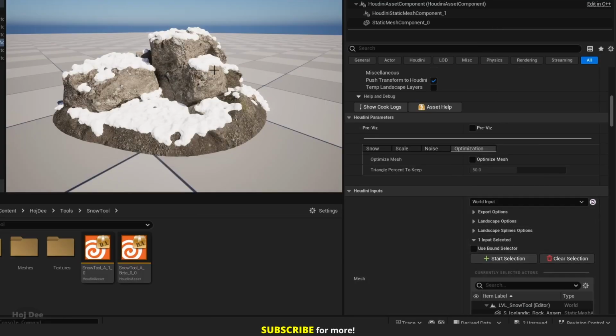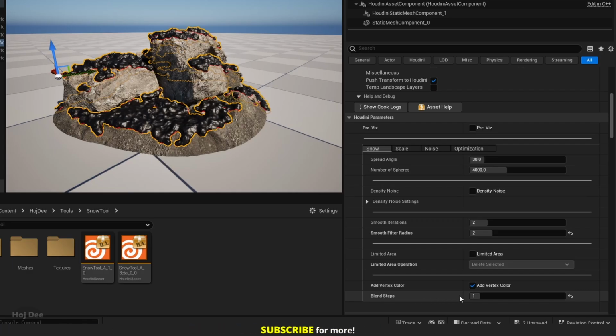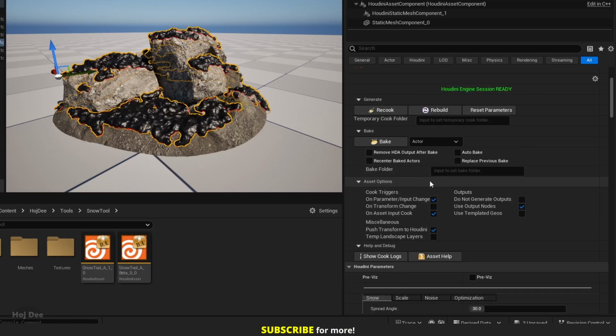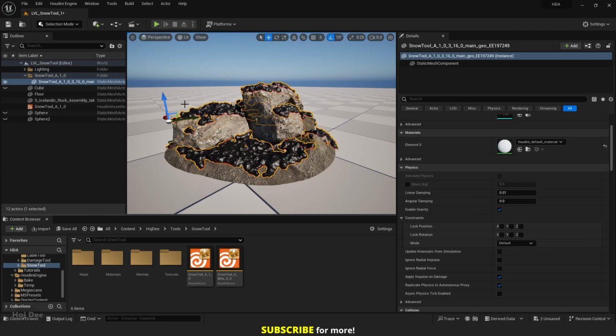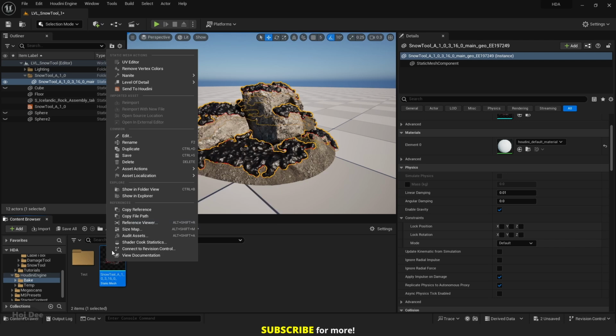After we're happy with how it looks, we should bake the digital asset into a mesh. But before that, under the Snow tab, let's enable the Add Vertex Color option and make sure the blend steps is set to 1. Scroll up and click on the Bake button. And it's done. Here it is in the outliner, and if I press Ctrl B to browse it, here it is in the content browser in this directory which Houdini creates. So let's convert it to nanite.